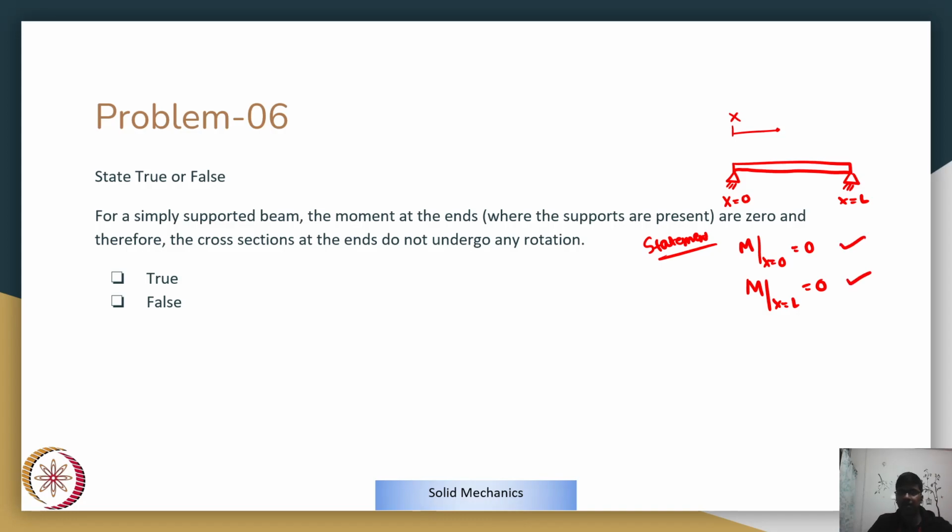So both of these things are actually true here, because you only have a line force. If you think about it along the depth direction, you only have a line of force acting along it. And if you take the moment of that line of action about any point on the support line, you would see the moment necessarily vanishes to 0. So there is no moment coming from the simply supported end.